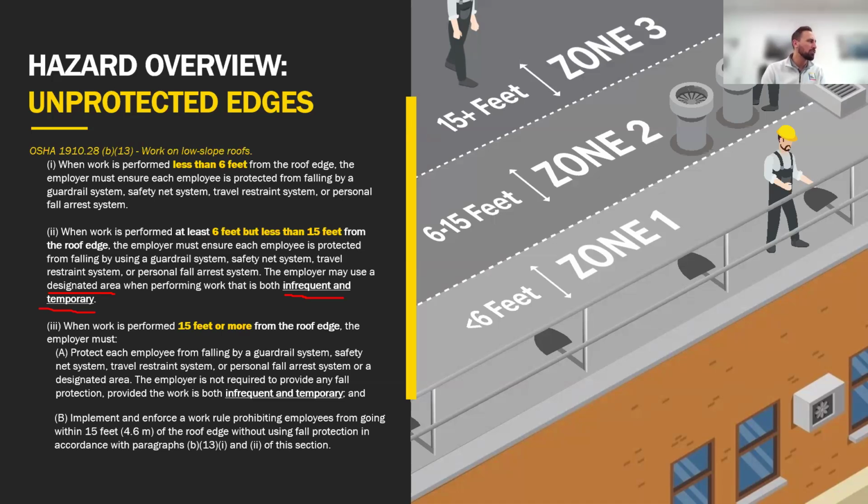Here are ways that we like to help employers enforce the rule. Most popular way, the training is, guys, there's 7 units on our roof that are within 15 feet of the edge. Each of them have a corral or guardrail around them. You're required to go in from the back of the corral, do your work, come out of the corral, which will deposit you 15 feet away from the edge. You travel to your next destination. You go in the corral, you come back out. We don't just put guardrail along the edge because you could just go from one and then just walk straight to the next one. So we're not enforcing that.